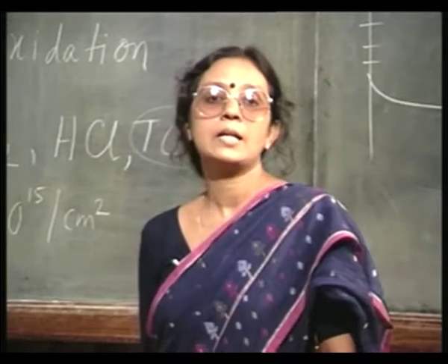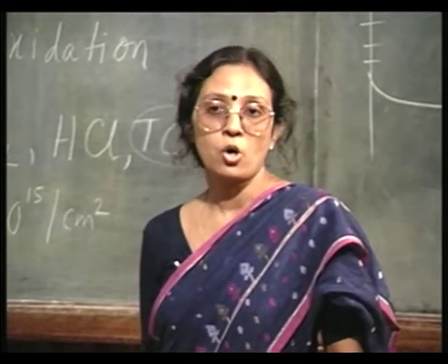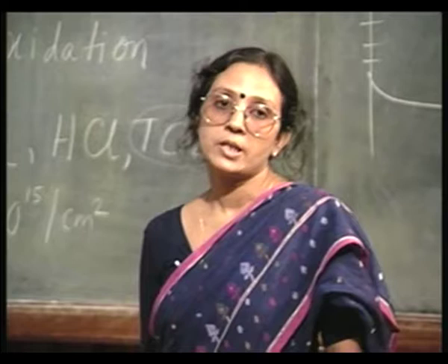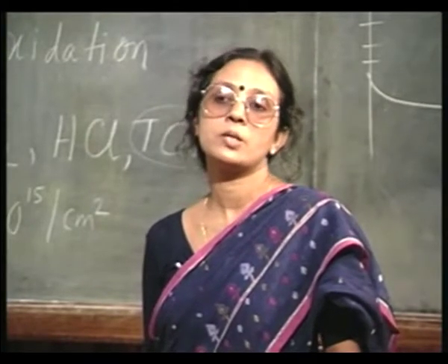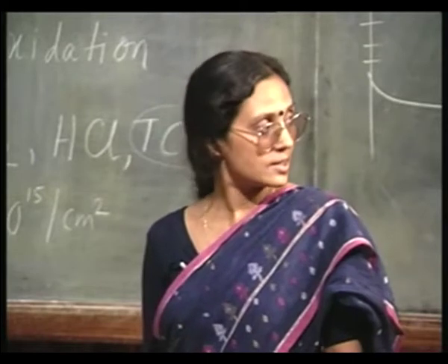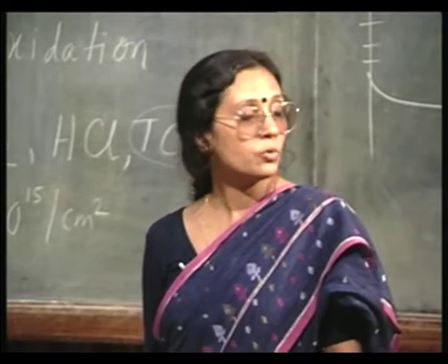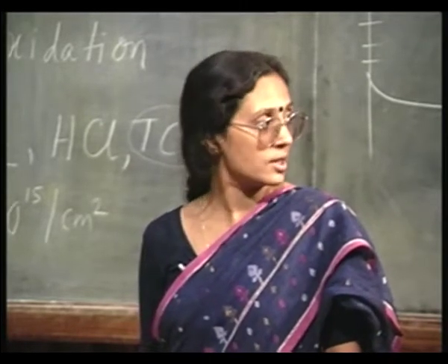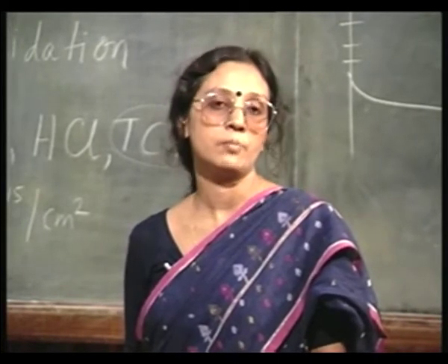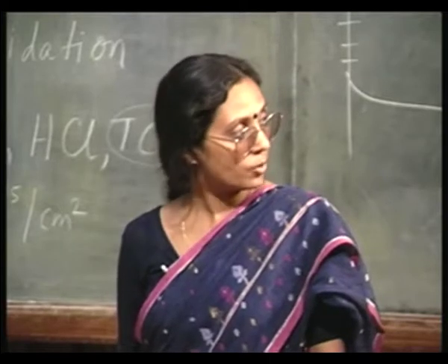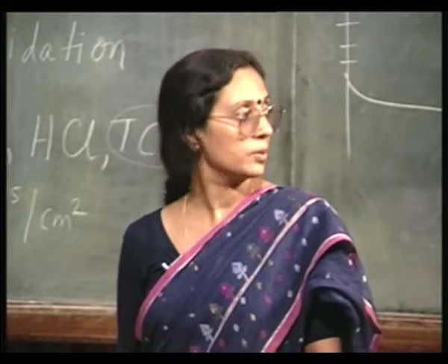Today, at the end of the oxidation process, always before taking out the samples, nitrogen flushing for 15 or 20 minutes is carried out. This is done in order to remove the traces of oxygen before the temperature is lowered. So, that when finally the temperature is lowered, there is no possibility of having incomplete oxidation.